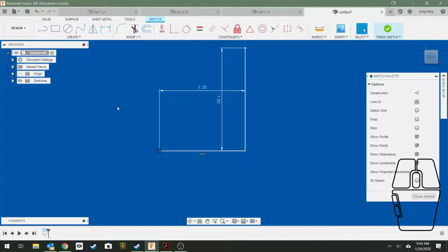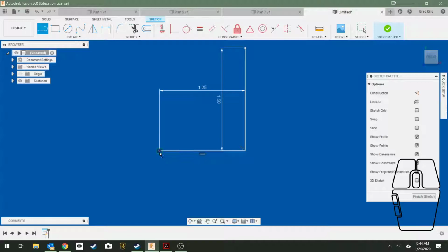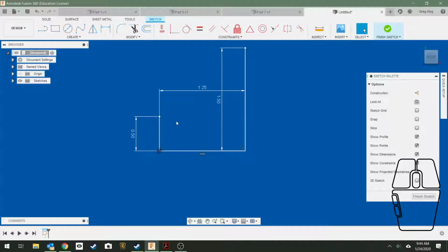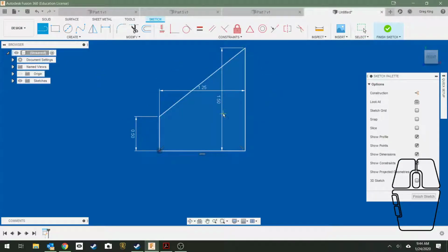All right. Now, diagonals. When you aren't given angles, it can be difficult to draw a diagonal. The best way to draw a diagonal with any technical drawing typically is to connect endpoint to endpoint. To connect the endpoint to endpoint here, I'm going to actually come up here and draw this piece first. And that's 2/4 or half an inch. And then I'm going to connect from here to here. And I get that shape.